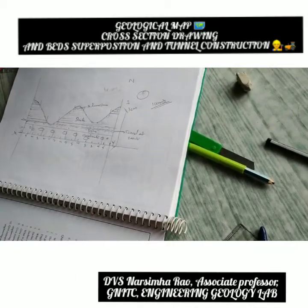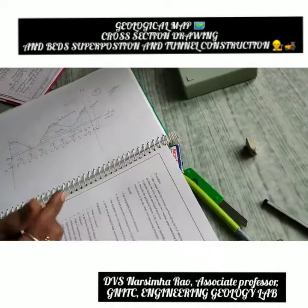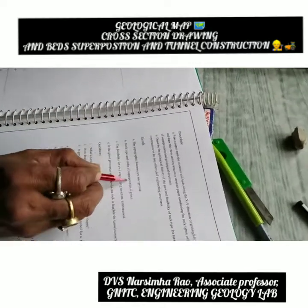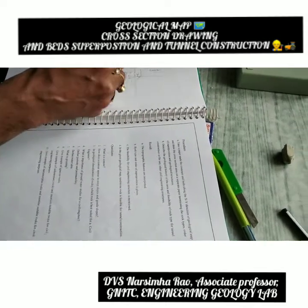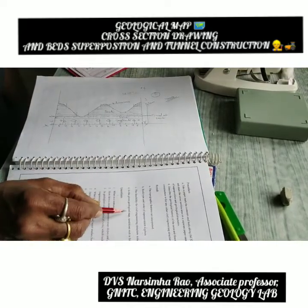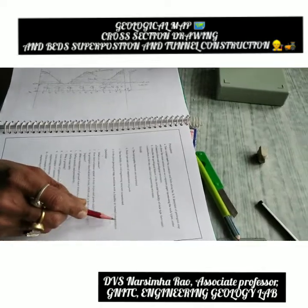Okay, so what is the result? What you are seeing? The topographic features are interpreted. Rock type and order of superposition are given. Okay, and feasibility of the civil engineering structure is mentioned: at the sandstone, where the tunnel is passing at 200 meters, and in the given geological map, sandstone rock is suitable for tunnel construction.